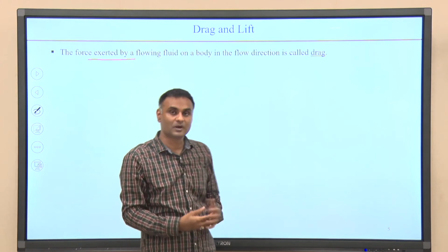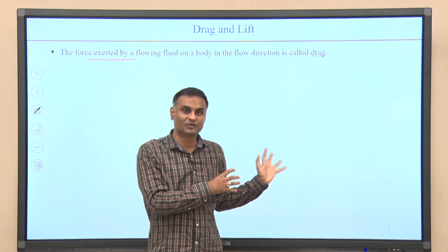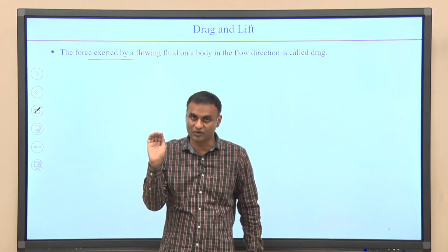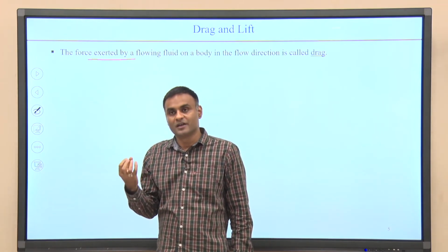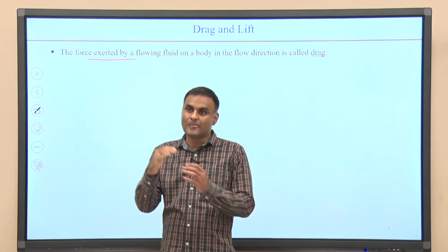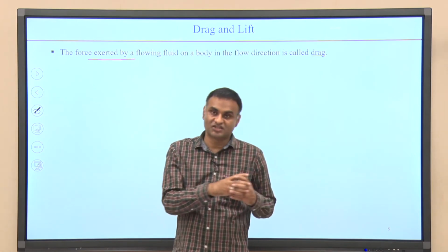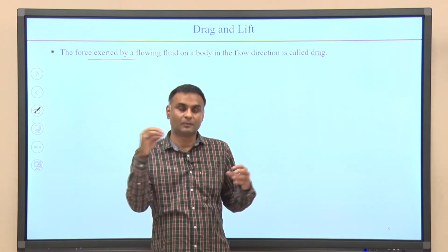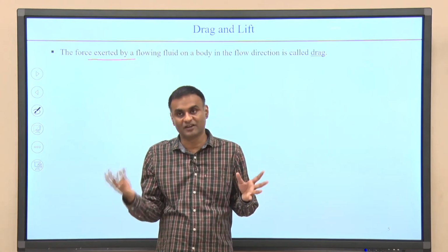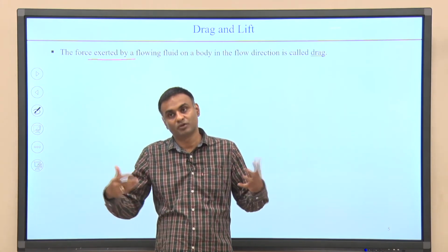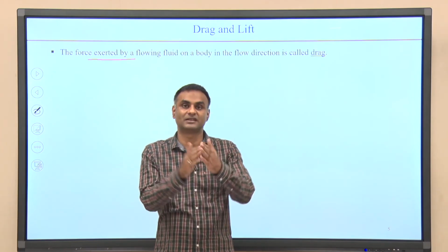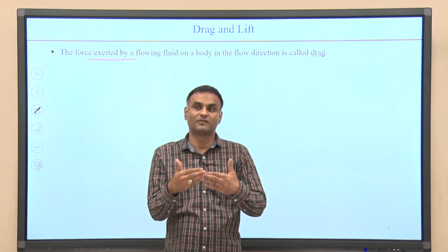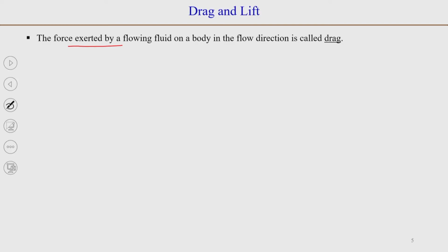So, the term drag comes from there: the force that a body in the flow experiences. Now, there can be several cases. The fluid might be moving, or the body might be moving and the fluid stationary, or both are moving. When we consider drag, it is the relative velocity between the fluid and the body.